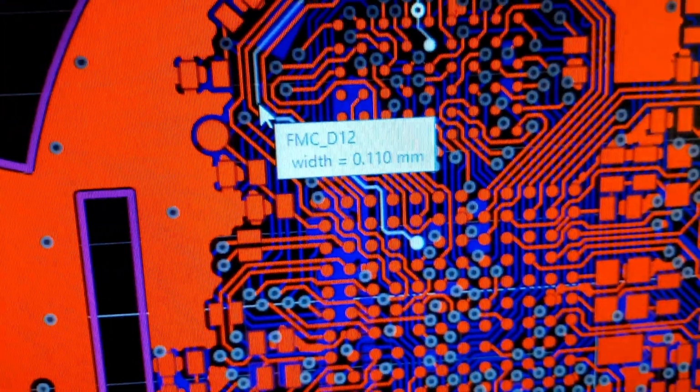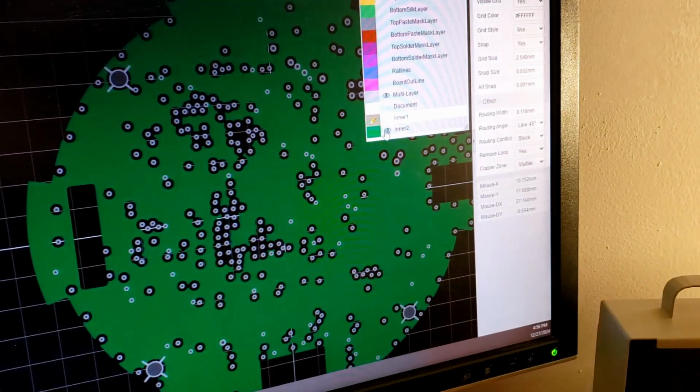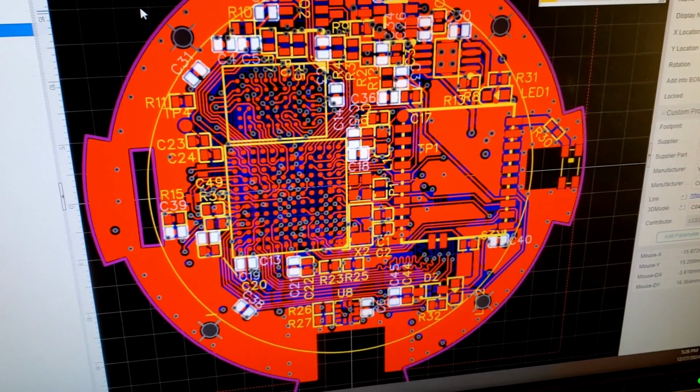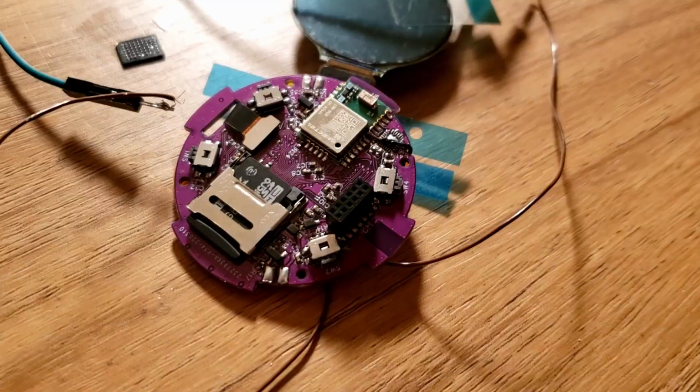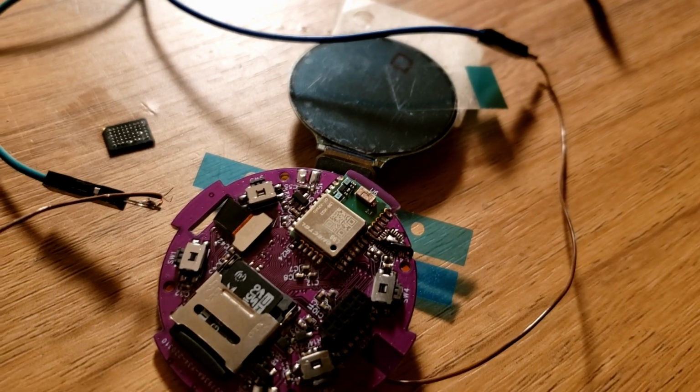The return paths for these high-speed signals could not transfer through local shorting vias, as my reference planes were at 2 different potentials, power and ground. Instead, they would have to find the nearest decoupling cap acting as a DC block. Because of the large amount of traces, even greater crosstalk would theoretically be introduced by the shared return paths.